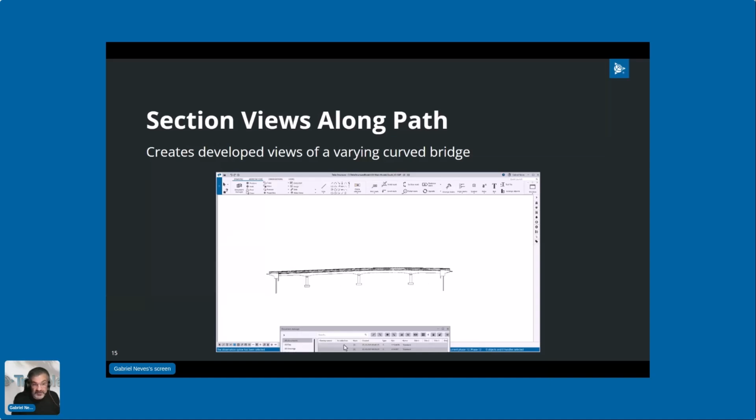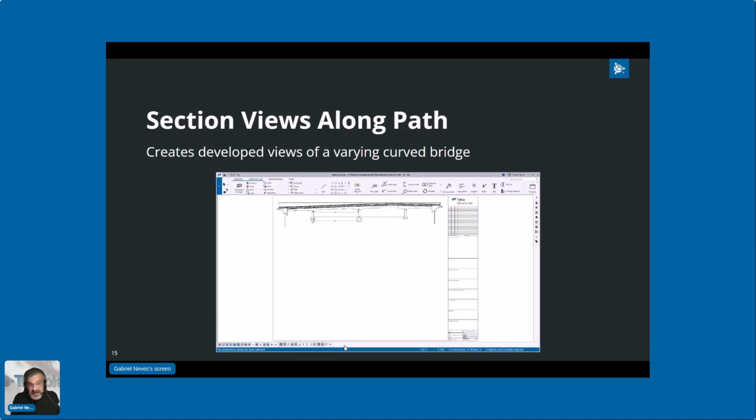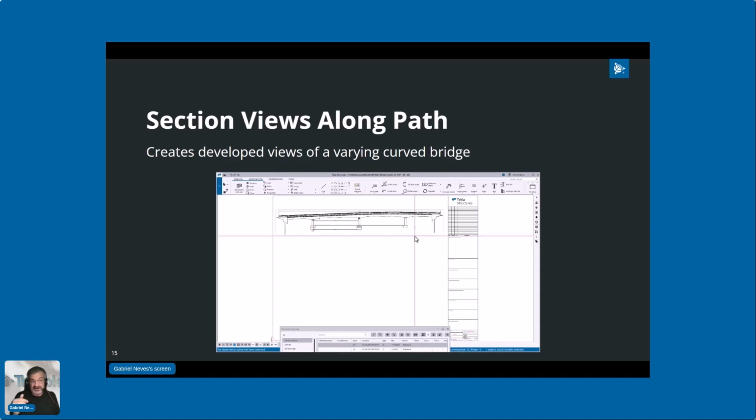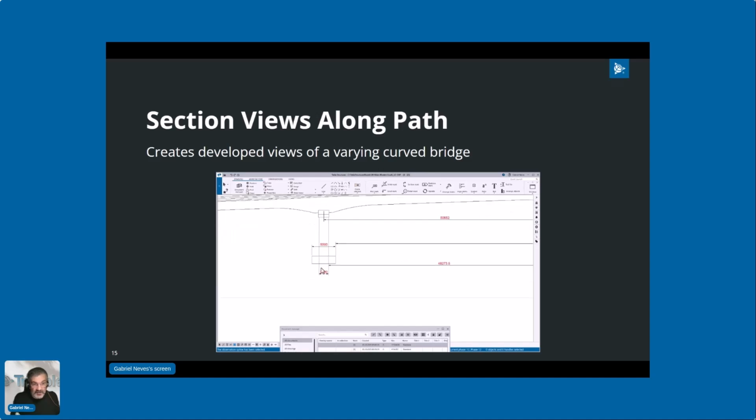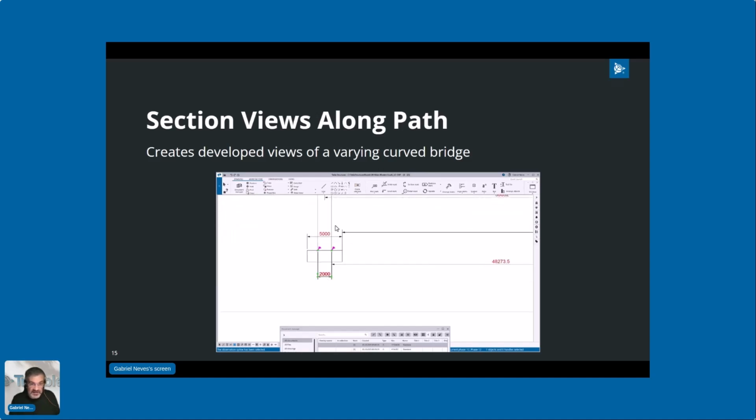We just copy the view to a new GA, and that will be kind of as a reference, which means if we need to move the view around, we have the main view because it was copied, and we can move that. And then with Tekla 25, now we can place dimensions across views. With the older versions of Tekla, we couldn't.